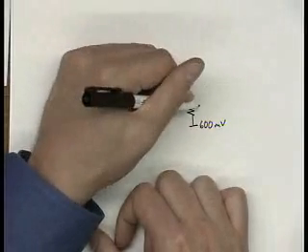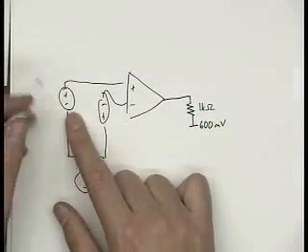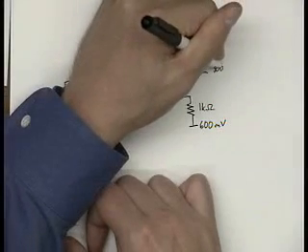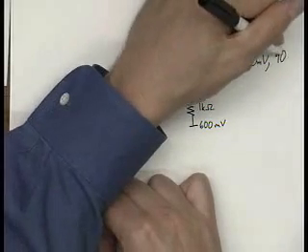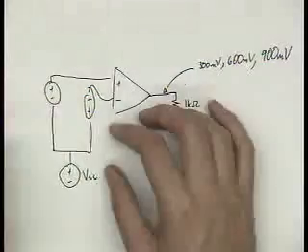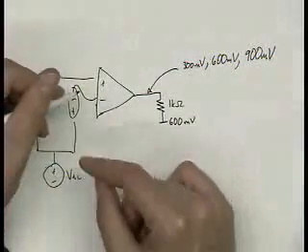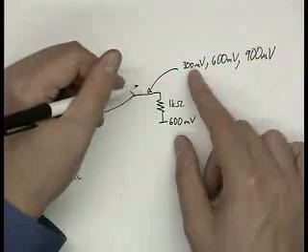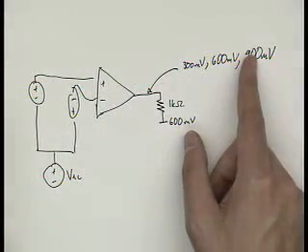If you look on the schematic, this is 1K ohm. Our test bench will figure out what voltage to apply to get this to 300 millivolts, 600 millivolts, and 900 millivolts. Okay? So we've got some funky test benches in here that'll do that for you. And what you need to do is make sure that the gain at each of these bias points, in other words, the small signal gain at each of these bias points, is still greater than 1,000.